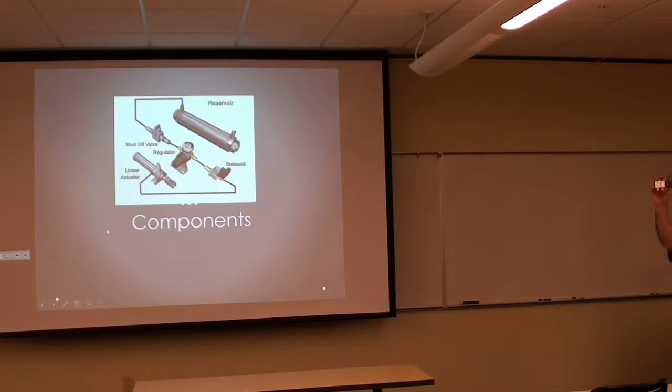So, what kind of solenoid valve? Internally piloted. It is internally piloted, but what do you see on this solenoid valve? Some red button. It's a 2 port, right? But how many actuators do I have? One. So what is the other actuator that you're not seeing? Spring return, right? Okay, so on a spring return actuator, what happens when I disconnect power? It goes to a default. It goes back to its de-energized state, right?